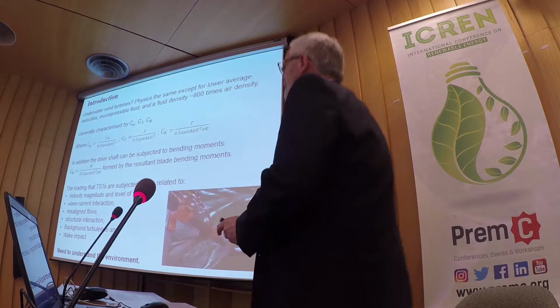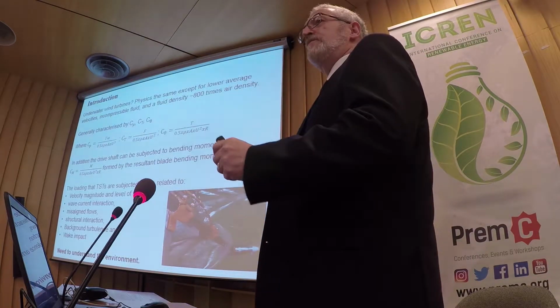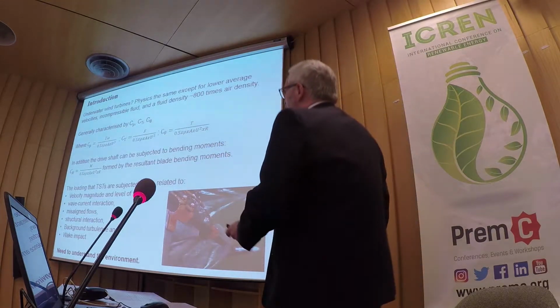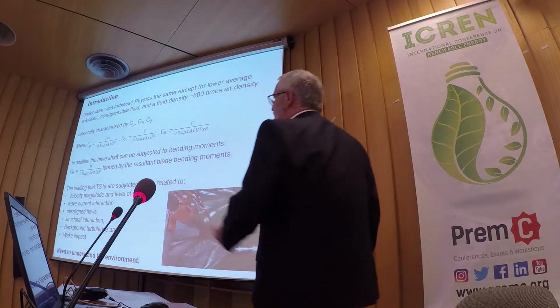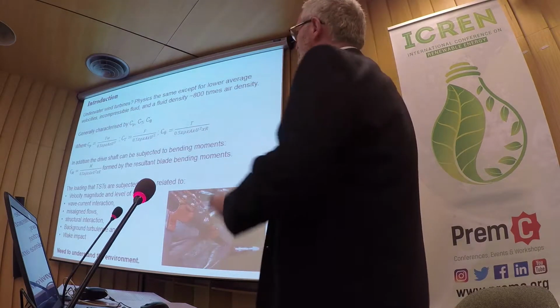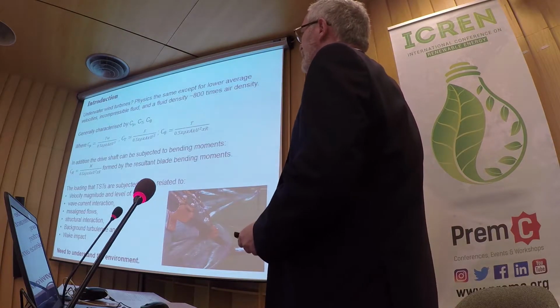One of the issues with this, though, is because of the density, the loading on the tidal stream turbines is quite severe. So we're interested in what's the velocity magnitude. Now, power, great, it's a cubic term. Thrust is a squared term, as is the torque coefficient.